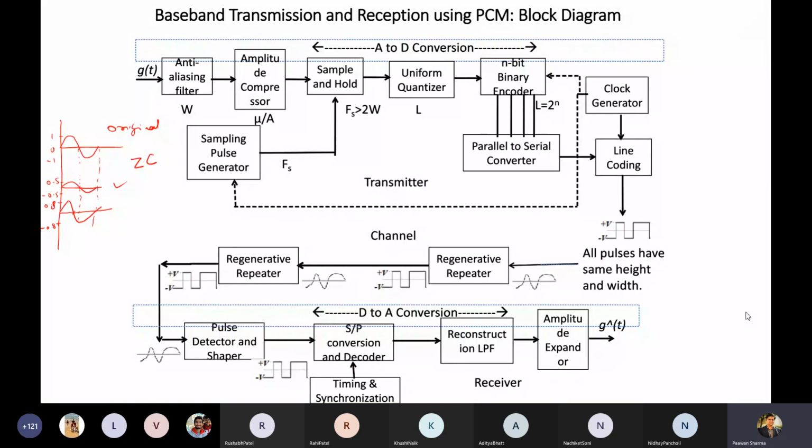It is passing at different points, or it may expand also like this. If a signal does like this, the zero crossing is changed, meaning there is a distortion, a change in the shape of the signal, and change in shape is not good because we do not know exactly when the phase reversal happened in time, so we lose this information and it is not good.